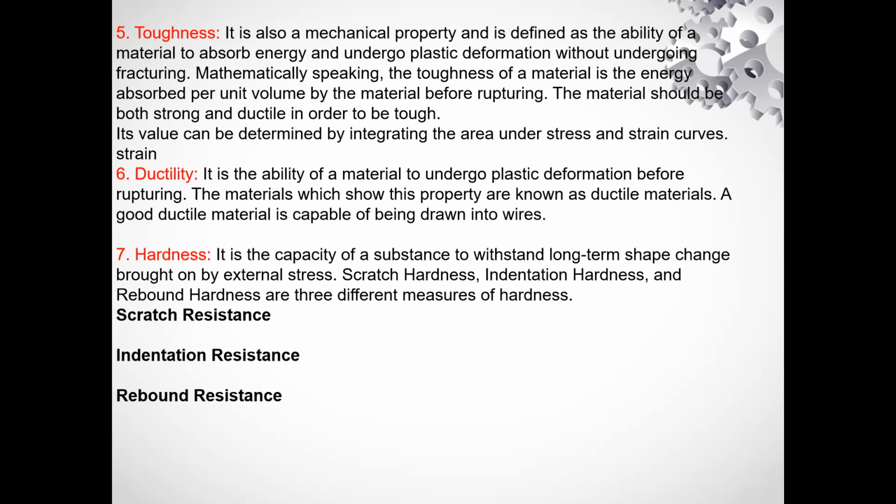Coming to toughness, simply to say, it is the ability of a material to absorb energy and undergo some plastic deformation without fracturing, before going to fracture. So how much plastic deformation is there? Let me find that out in our toughness. How do we find the toughness? Let me tell you.